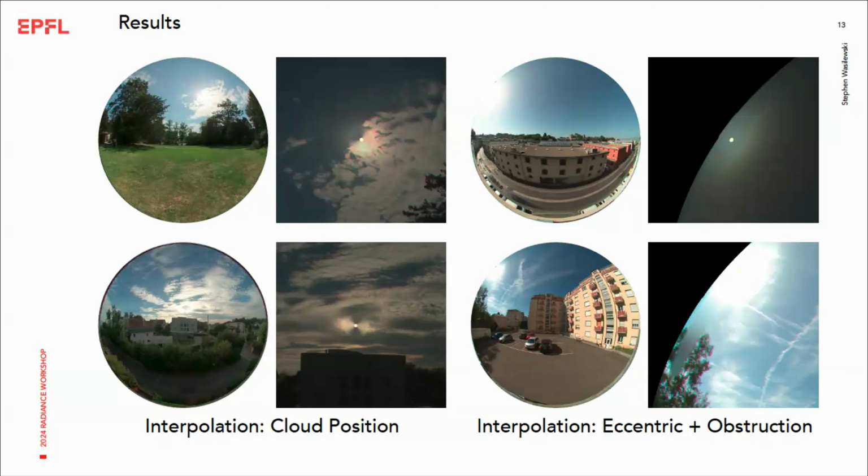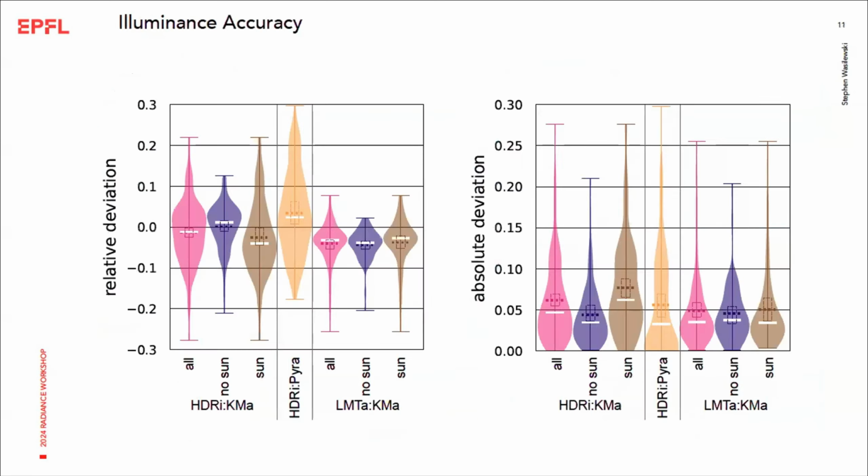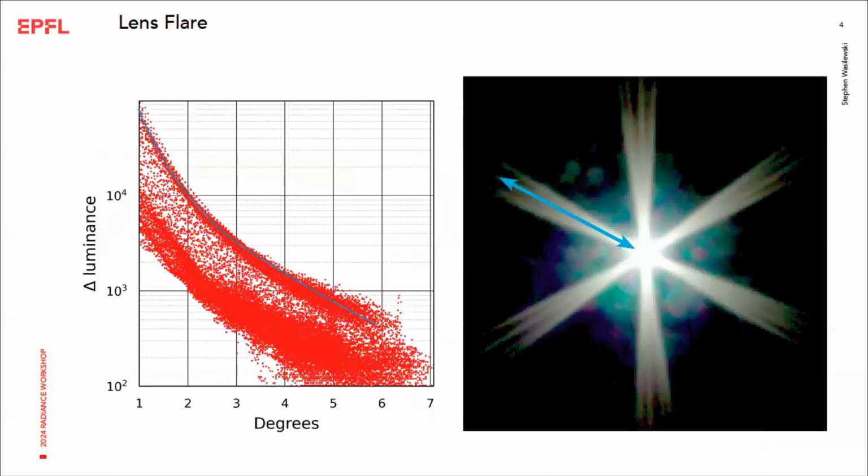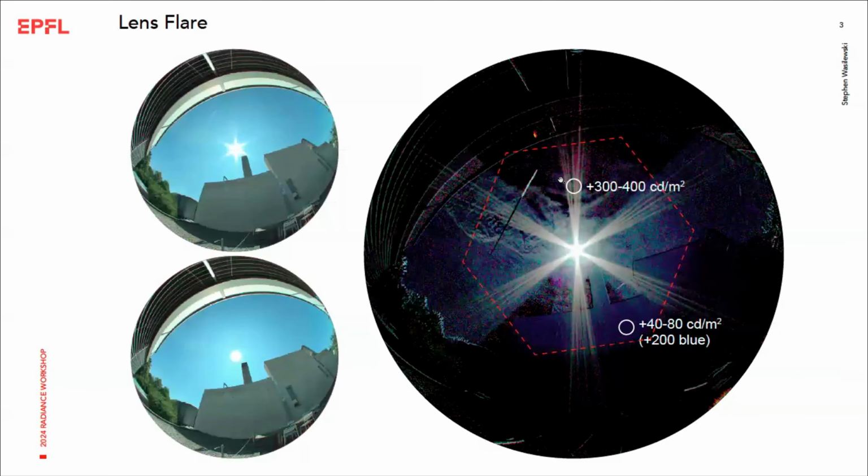Yeah, I think the lens flare has a pretty minor effect on energy, but it does have an effect on glare analysis. But with glare analysis, you can do basically the equivalent of peak extraction or something. There are simple, artifact-laden ways of doing that. Because if you look at the 300 candelas per meter squared, it's not going to change your glare analysis there, right? That's a really small error, but it's visible, especially if you run it through Pecan or some other human adapted tone mapping. It's going to become really present.